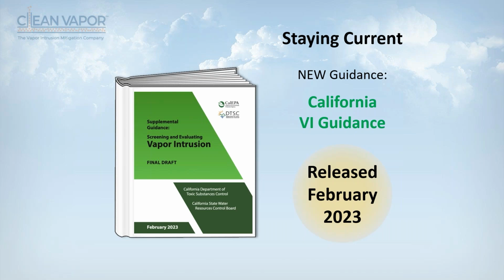And then the consultant that they hired to critique the system did the critique based on 2008 standards, which created a bunch of unhappy people. So make sure that you have the most recent document so you can set the end goal of what the performance for your system is going to be. And achieving the specifications in terms of indoor air quality and pressure differential that's specified in these documents is absolutely critical.